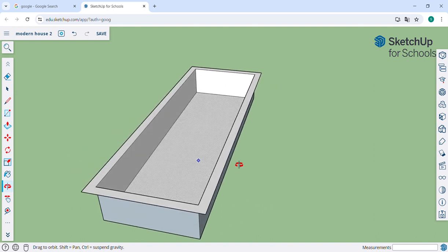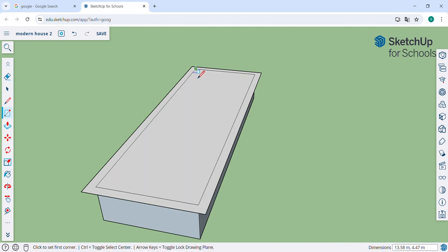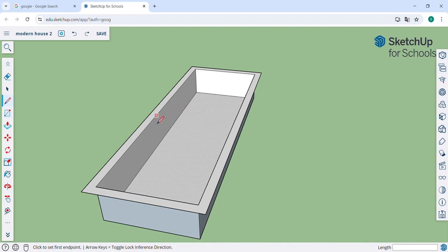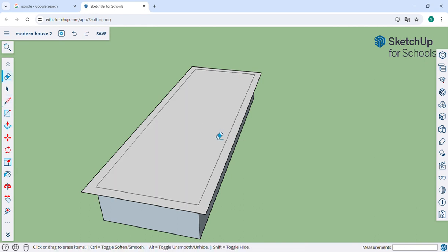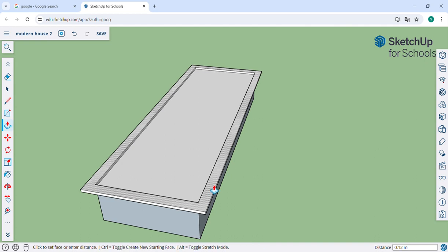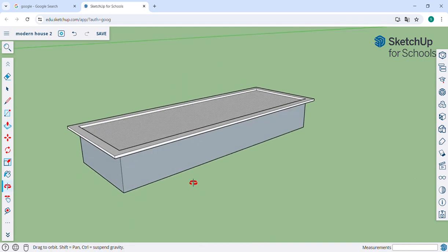Now, I want that swimming pool to be completely covered. So how do we cover an empty space like here? You could use a rectangle, but you can see that it might be a little bit more difficult. Or you could use the L tool. So line tool, you go from one side to another, and then you erase whatever bothers you. Keep in mind that we can brush this after, to make it transparent water, but to avoid a fusion between the water and the sides, we're going to push this slightly up, and now it's going to look like a swimming pool.